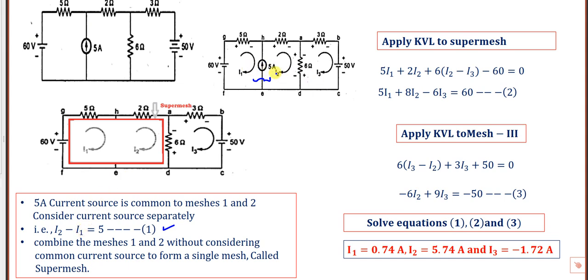Suppose the direction of the 5 amp current is given downwards. Then it would be mapping with I1, so I can write I1 minus I2 is equal to 5. But in this problem, this 5 amps is mapping with I2, so I can write I2 minus I1 is equal to 5 amps. Always, while writing in the calculator, you should write the coefficient of I1 first.